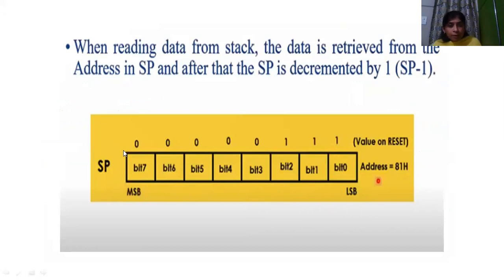For reading data from the stack, the data is retrieved from the address in the stack pointer, and the stack pointer will be incremented by 1. For writing data to the stack, the stack pointer will be decremented by 1.